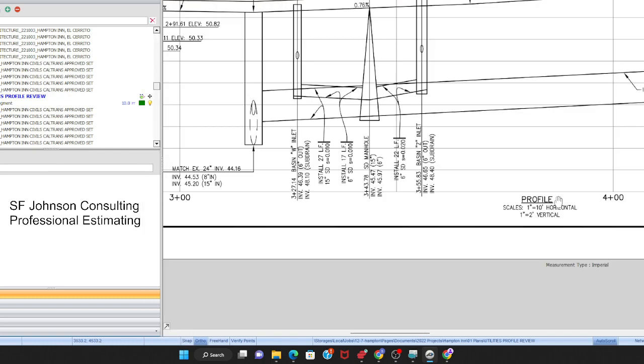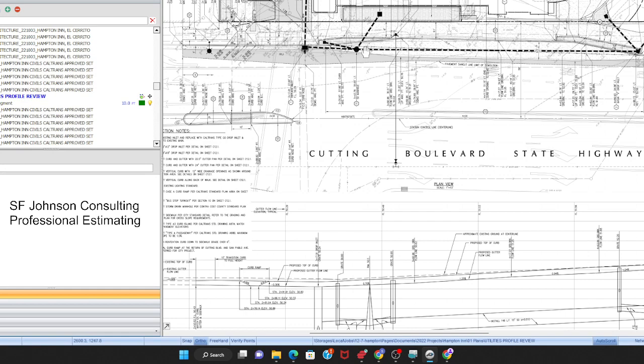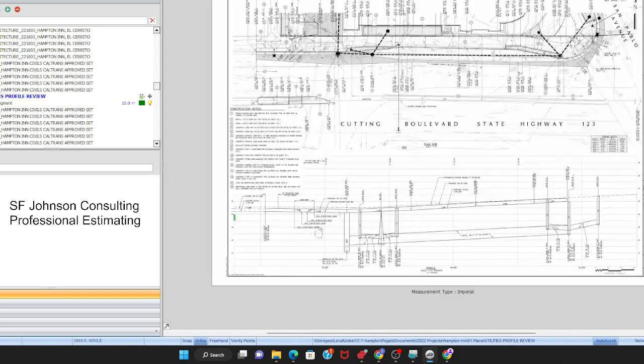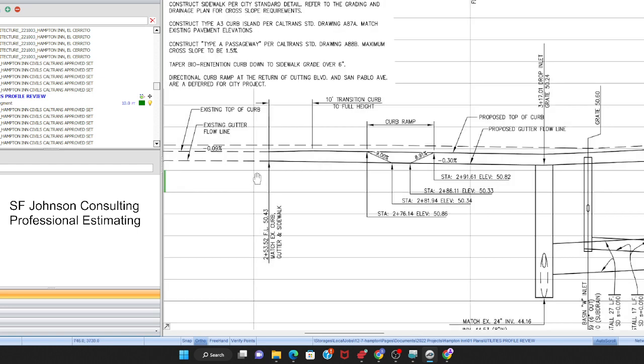Okay, so now what can I do? Well, from our plan view, we're always going to give the plan view a foot on either side of the pipe. So that's 2 feet. As far as this width, the length, and the profile view helps you determine the width. And those are your 3 dimensions.